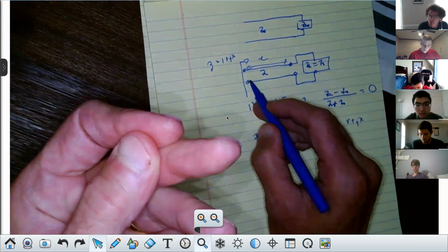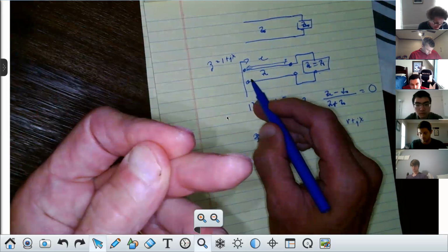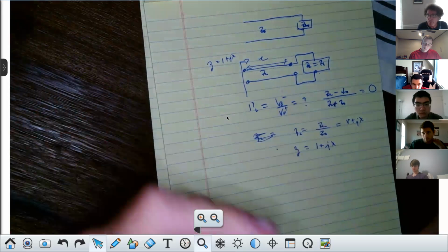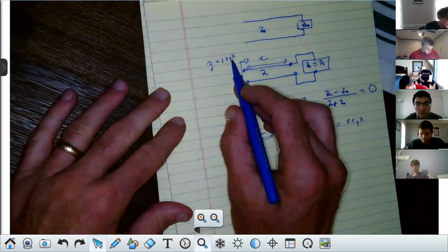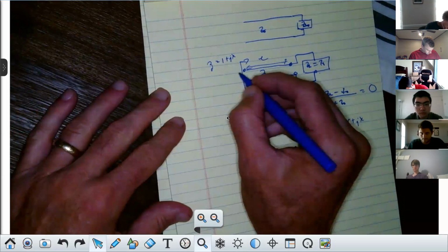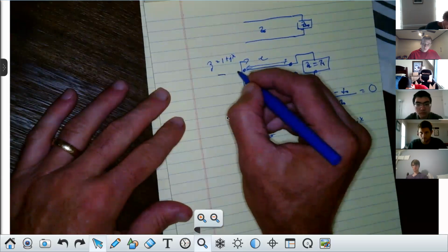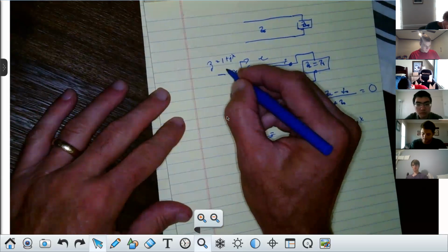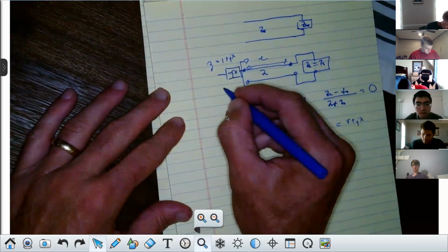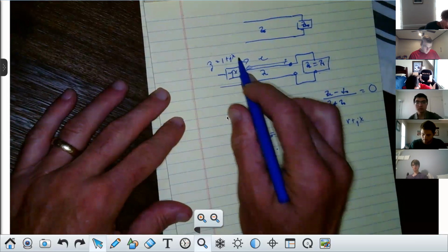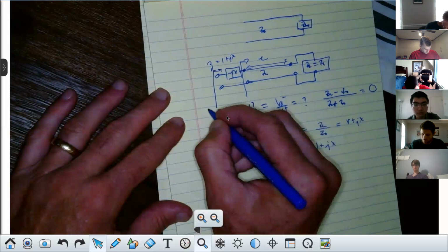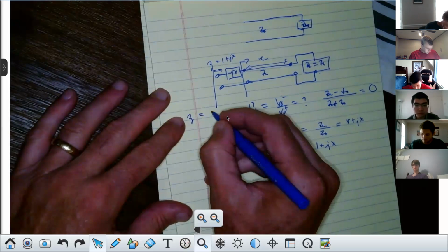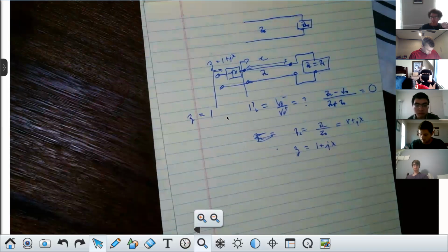X could be a negative or a positive number, but I have a real value of 1, right? At that point, I'm going to add an element, this time in series, because it's an impedance, that will be minus JX. So when I add minus JX, the normalized impedance here will be just 1. Do you follow me on the other side?